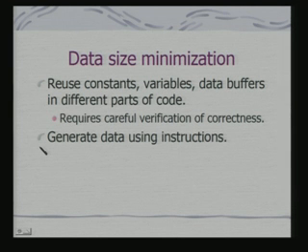What is the advantage? The instructions would occupy less memory. Instructions go into, say for example, flash. So, the amount of flash memory required would be less, okay. But when it is generating the data, you can say that okay, data size would be large, fine. If the data size is large, we can accommodate the data in a DRAM, okay. But the point is, I might not require the entire data for all computations, okay. So, I need not have the complete data stored a priori; write a program to generate the data depending on